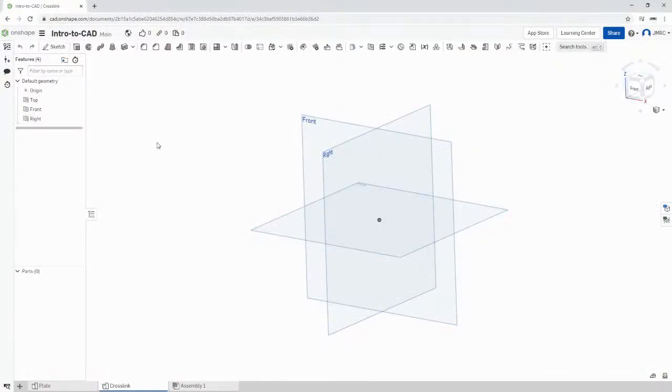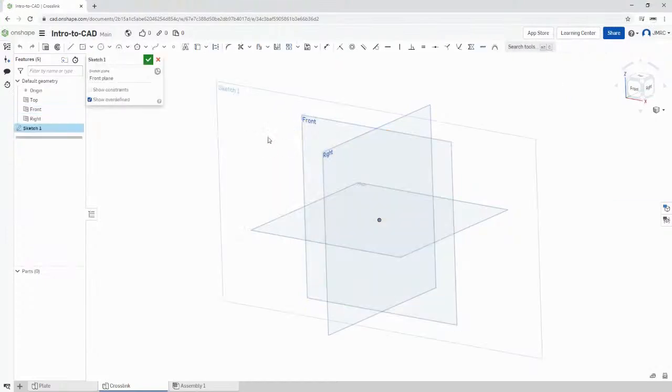So last time, we headed over to our toolbar and selected sketch. Let me show you another way, which is selecting the front plane in our graphics window. Once more, it is currently highlighted in orange. So with that, I can right click and select new sketch.